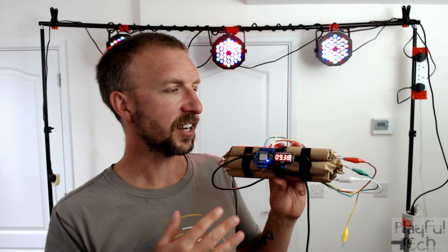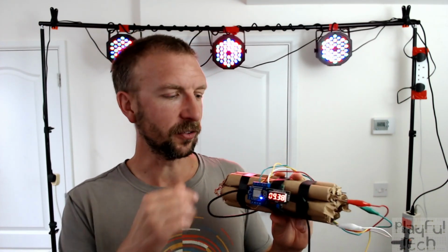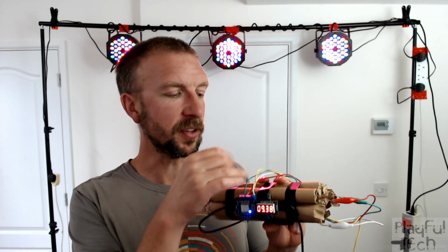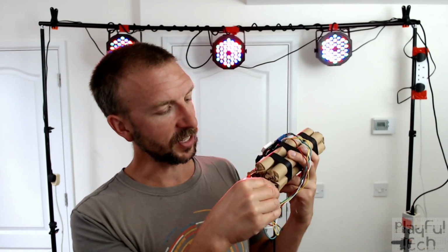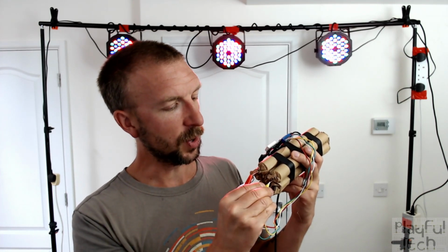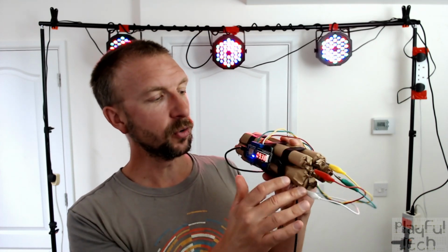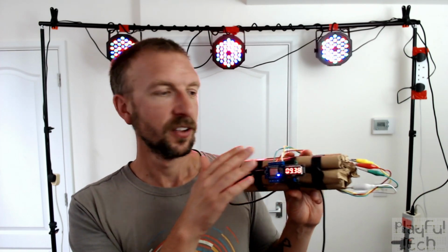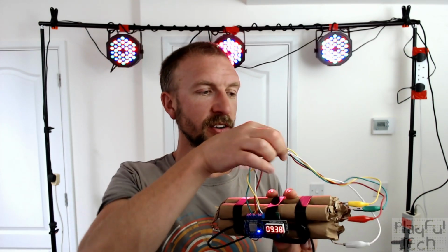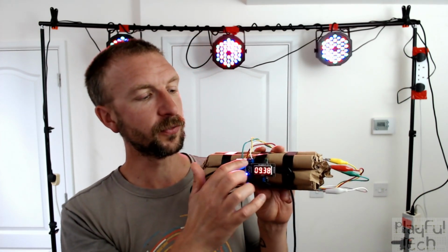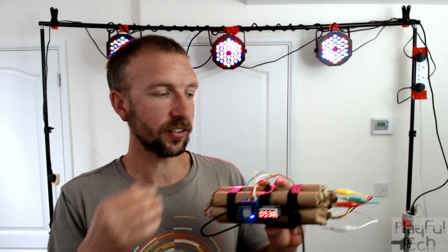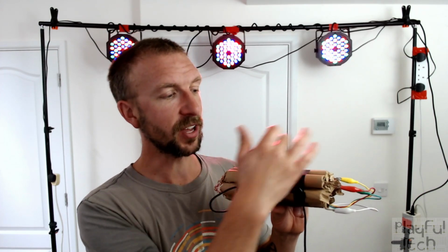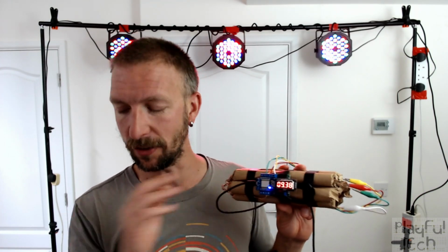So the way the circuitry works in this puzzle, we've got 4 GPIO pins here. When they're connected to the bomb, this bomb basically has copper wires going through it, and these are all connected to ground. So when the wires are connected like this, all of these 4 input pins at the top here are going to read a low signal. That's how we know that they're connected, because they have a complete circuit all the way through to ground.